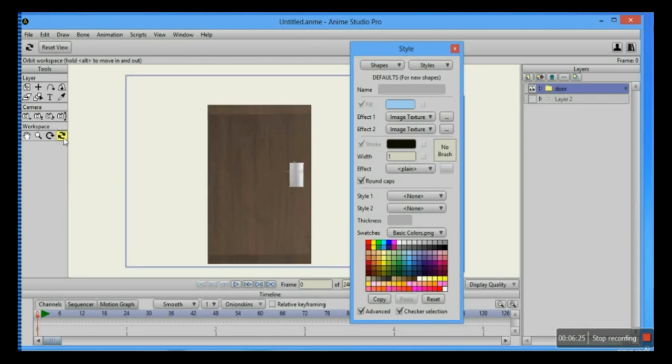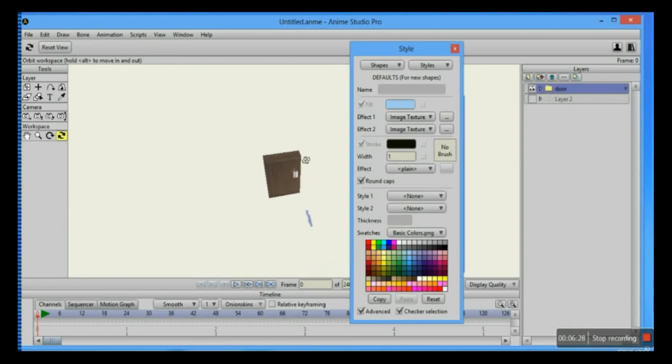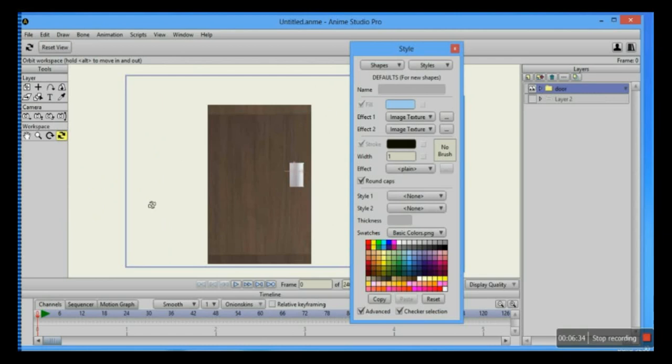So what I'm going to do here is to show you that in order to manipulate this door, this orbit lets you manipulate 3D in a workspace, but not to animate. But to animate, you're gonna have to go to frame 1 in the timeline and use the orbit tool, and these are set origin and this transform layer. These three will be very useful for you, because they're good in 3D objects, because they got X, Y, Z, which is the form of 3D, and which manipulates 3D. So I'm gonna start with set origin.